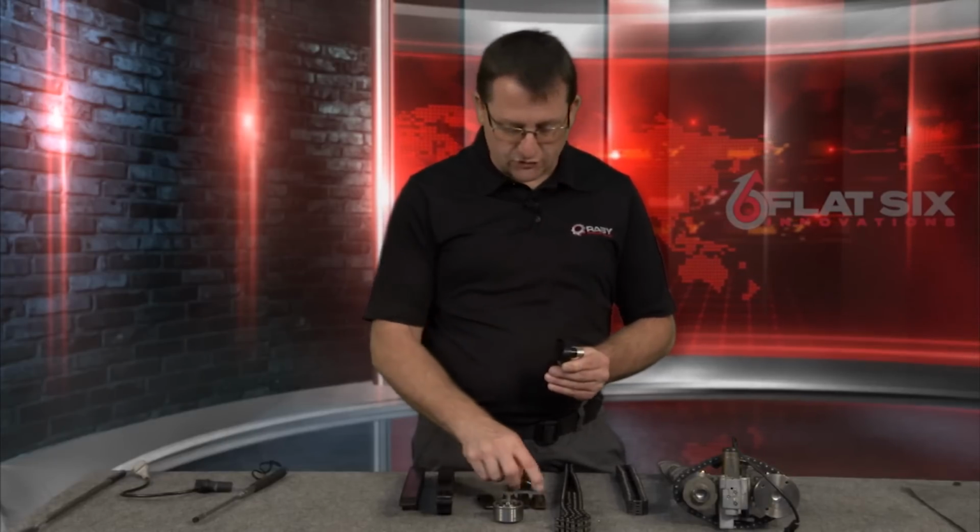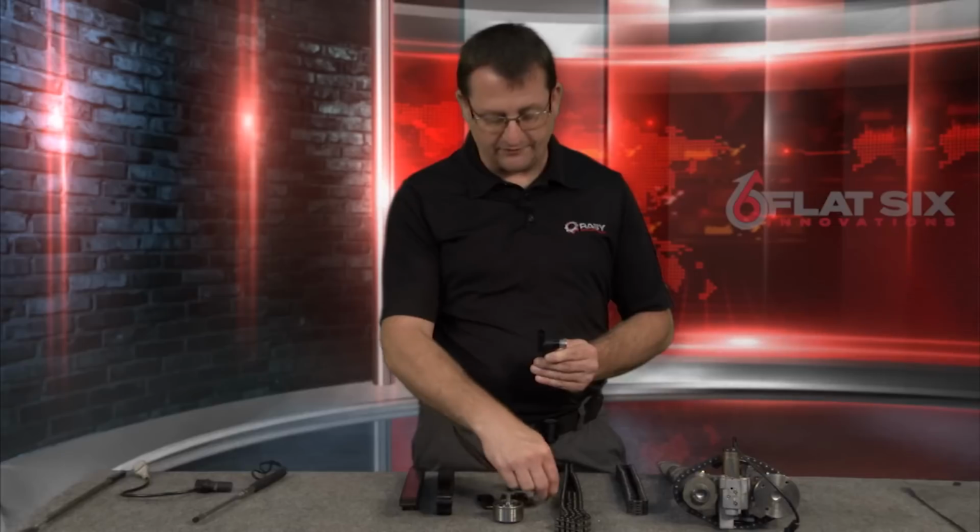My tolerance for that is 4 degrees, okay? So I don't want to do anything with an engine that's got beyond 4 degrees from a repair perspective. If it's beyond that, I have my customers sign waivers and understand that it's almost to the point where we're going to have to go in and change these wear pads on the 5-chain, because this is what's responsible for those big camshaft deviations in most cases, which we're about to go over in detail.